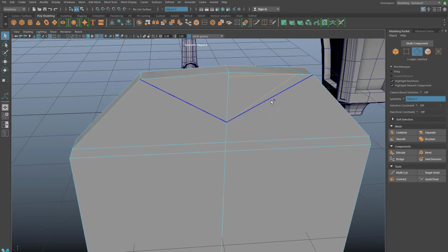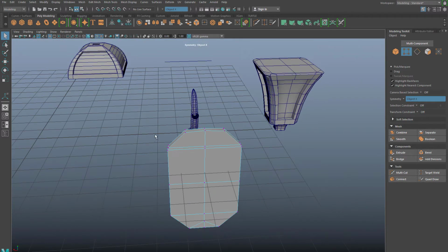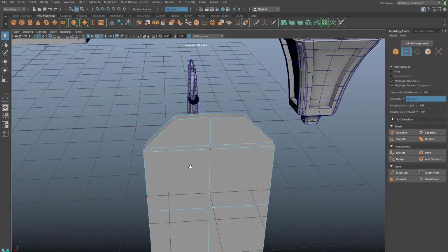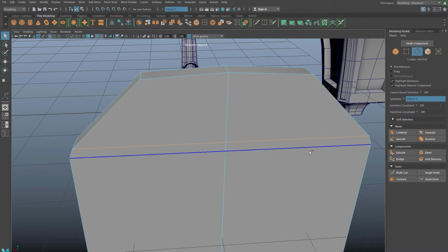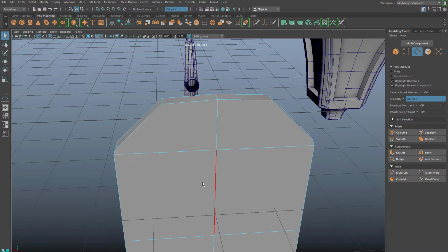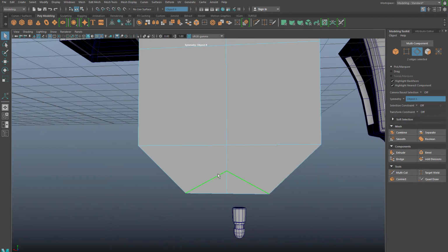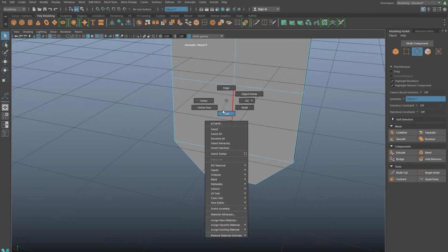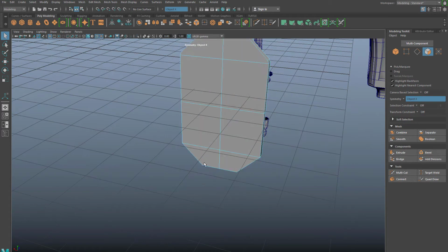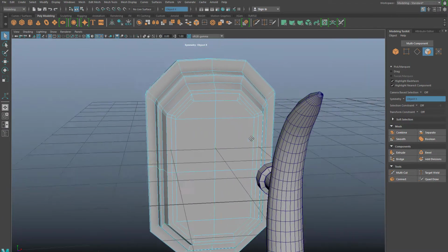As far as the back side here, we have all sorts of kind of strange edge things going on. Any extra floating vertices? Nope, not much. So back to edges. That should pretty well take care of that. And then if you're worried about n-gons, you can always come back and triangulate it. So bevel, and then it's been reduced.